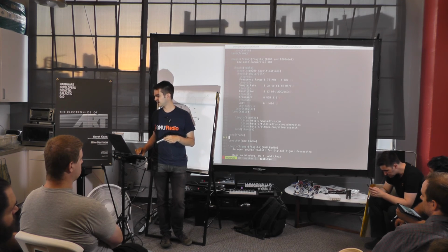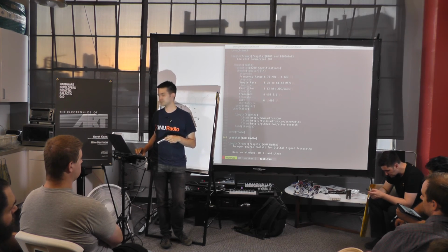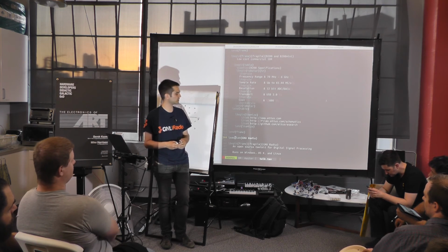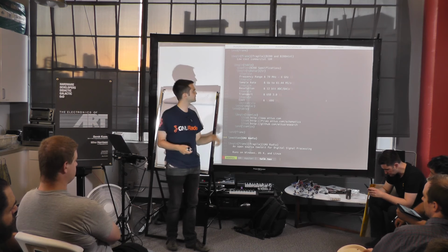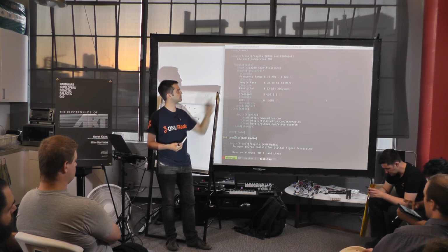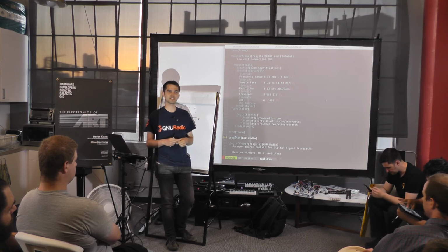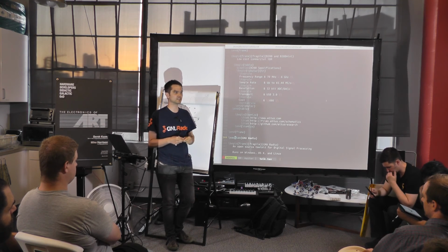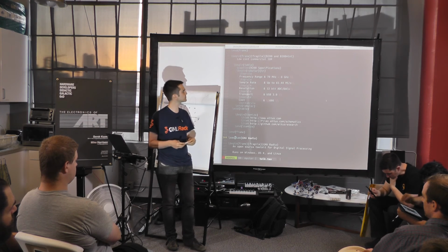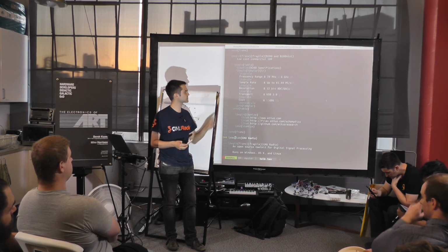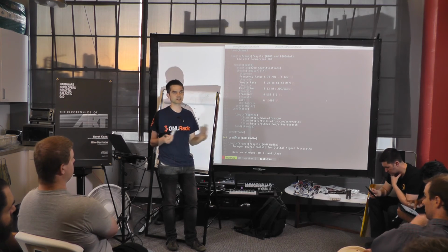And then finally, not entirely just as a shill for the company I work for, the B200 and B200 Mini, which I'll pass around in just a second, go from 70 megahertz to 6 gigahertz. You can sample up to 61.44 megasamples. That weird number is actually because it's very convenient for telecommunications. Some of the protocols that they use work at divisors of that. 12-bit ADCs and DACs, USB 3, and it's $680.